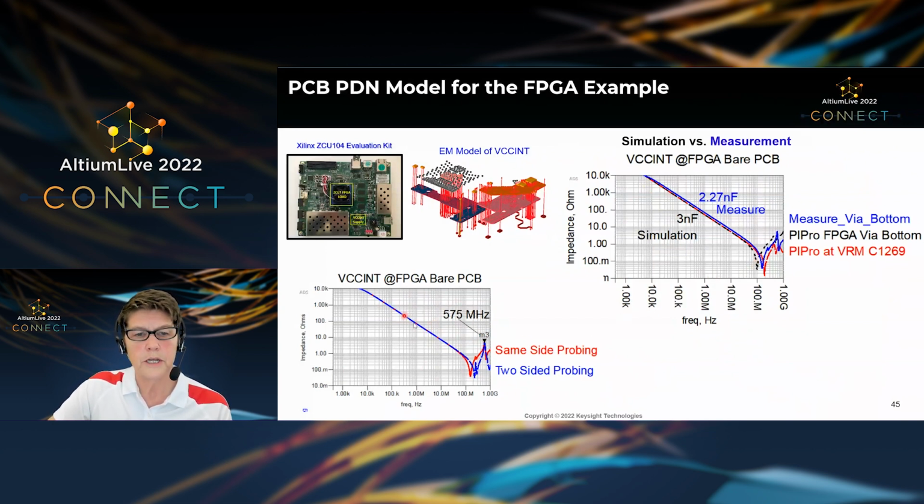The long story short here is basically I use this bare board measurement to really focus in on what's the capacitance that I'm seeing on this bare board measurement, and does that match with my simulation? And then if not, then I can look at my stack up topology and my dielectric constants and see if there needs to be some adjustments. At the higher frequencies, you can sort of look for some of the resonances, but again, sometimes the measurement techniques can make it difficult to get exact correlation with the simulation at the higher frequencies, depending on the calibrations.